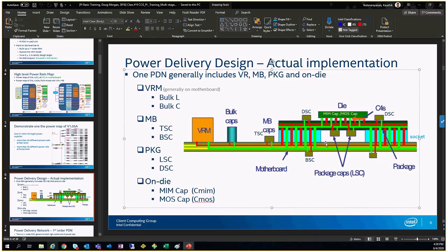Okay. So for the capacitors, why do we hook up only ports? We have our own models which are generated by Intel. Intel has its own model for all the capacitors, depending on the value. Pankuri will share them with you. We have a tool from which we generate those models, and we hook up those models at the ports.